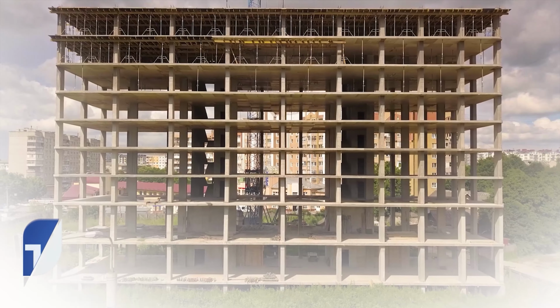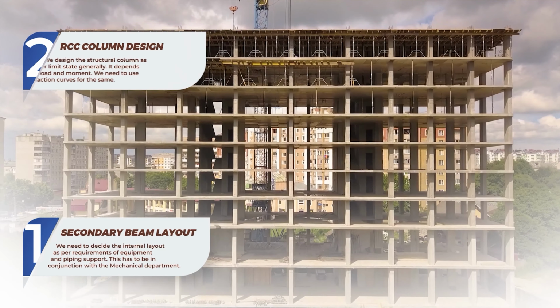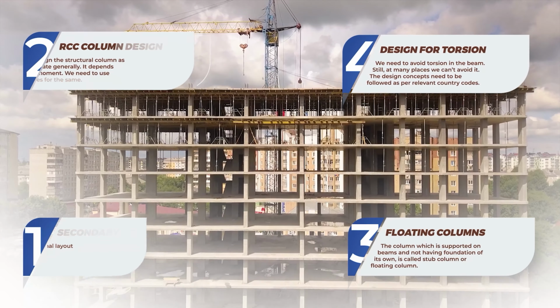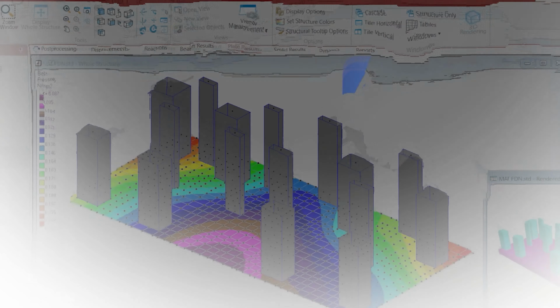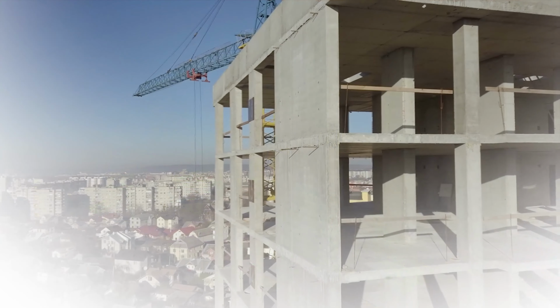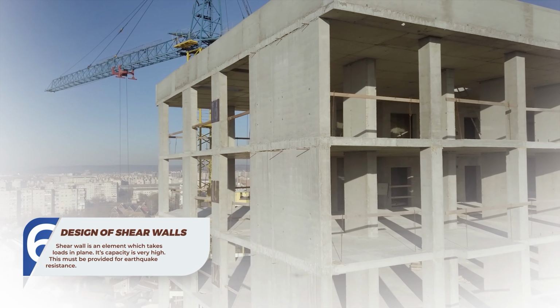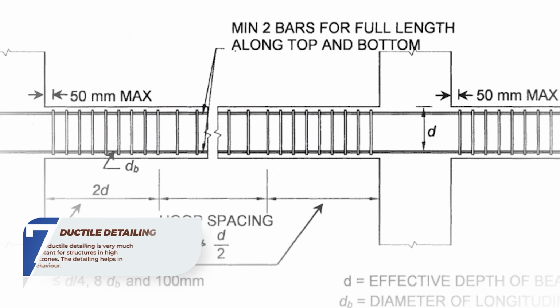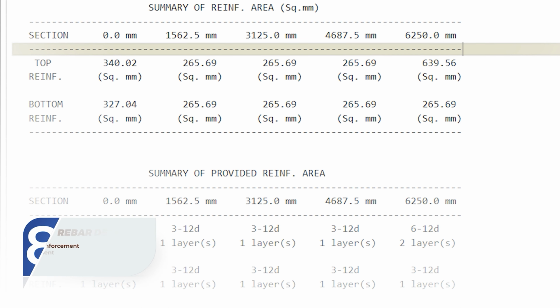In industrial RCC structures like administration building, control room, etc., we will be covering layout of structures, secondary beam layout, RCC column design, pedestal and tie beam design, floating columns, design for torsion, extract of plate FEM analysis results from software and its application for industrial foundation design, including mat foundation, design of RCC brackets, design of shear walls, ductile detailing as per IS 13920, rebar detailing from software output,